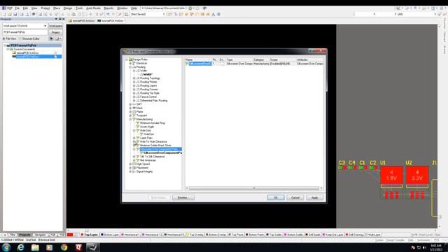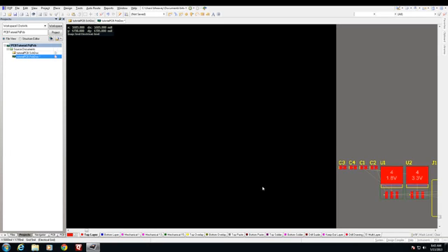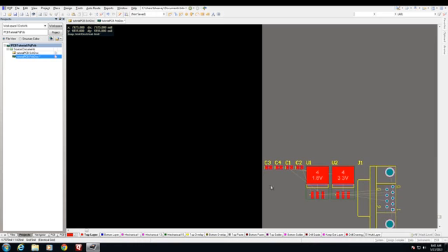Finally, we're going to modify the hole size here, because we've got large holes in our 9-pin connector and we need to go ahead and up the maximum so that they don't violate our rules. So we're going to take this 100 mil maximum and change it to 150 mils. With those three modifications, we'll hit Apply and OK. And now you can see all of the violations, the green colored pads have disappeared.